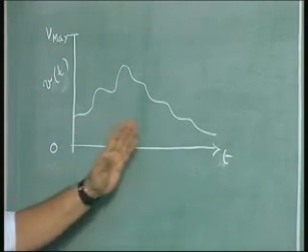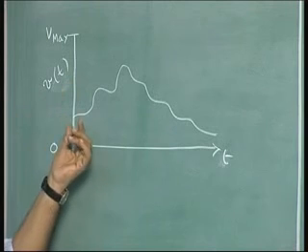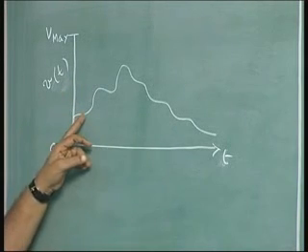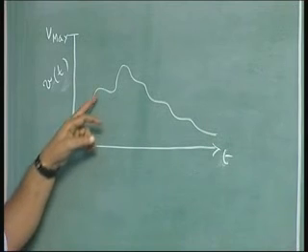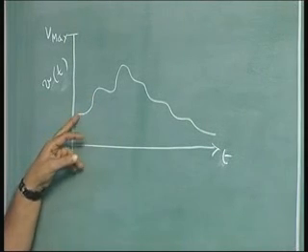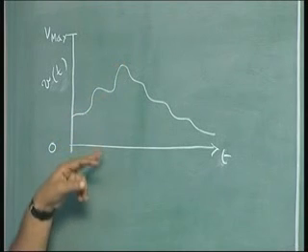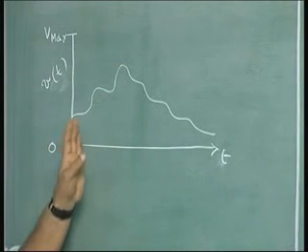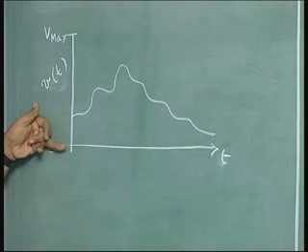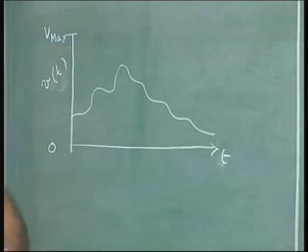And at any instant of time it can take any value, and what the instant of time is, is also not defined. I can make a measurement here and immediately at the very next instant of time, or I can do a measurement here and do it much later here. Nothing is defined here. This variation of a signal which can take any value between these two limits is called an analog signal.